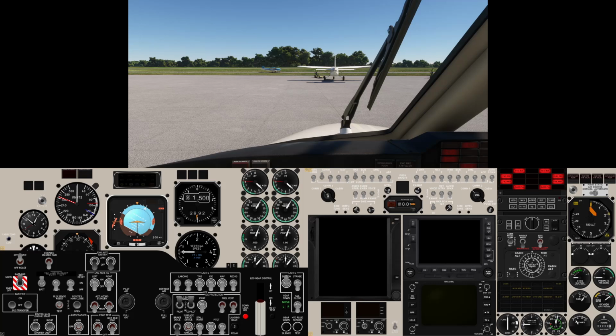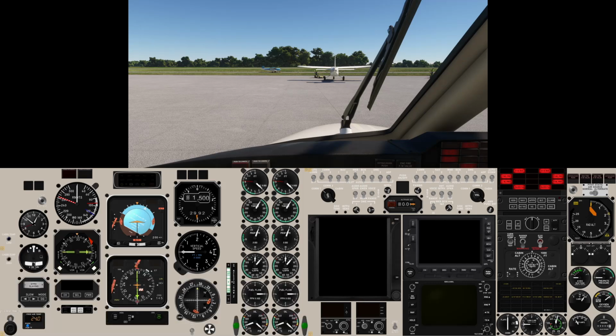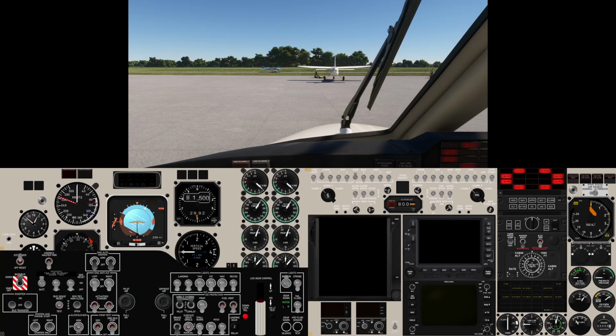So we're watching a little bit awkward here because we've got the NG or prop RPM. There is the fourth gauge down, so obviously the one on the right for the right engine, so we can see that there. Again, similar to starting any turbine, we're just waiting until that NG comes up and stabilizes.